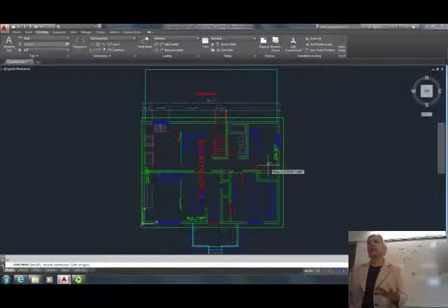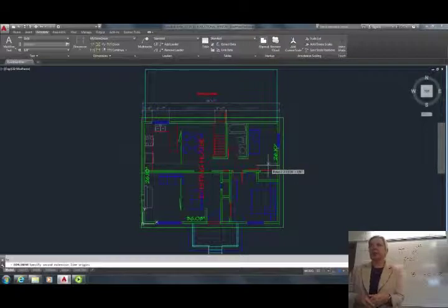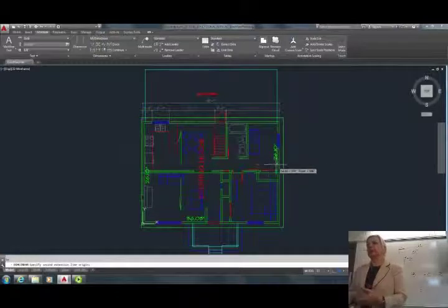You would say all interior partitions are 4-inch studs, 1/2-inch drywall both sides, and don't dimension them on a string. All exterior wall is 8-inch or 12-inch, and you have that information on your section. So I would not clutter our small drawing dimensioning each wall.